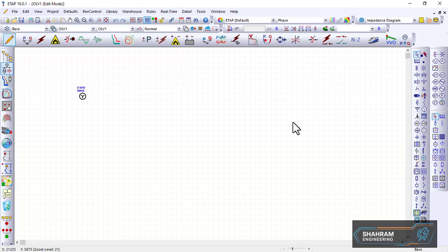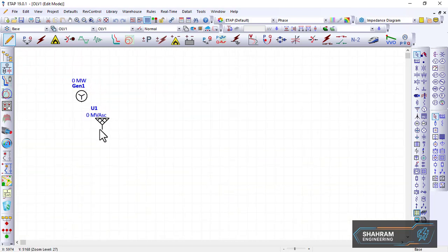There are two ways to set this slack bus. Remember, the slack bus is a reference bus. We can either select a generator or a utility grid. The difference between these two is that one is a generator and the other is a utility grid, which can also be called a Thevenin equivalent: a point in the grid, or a point of reference where we are connected to.